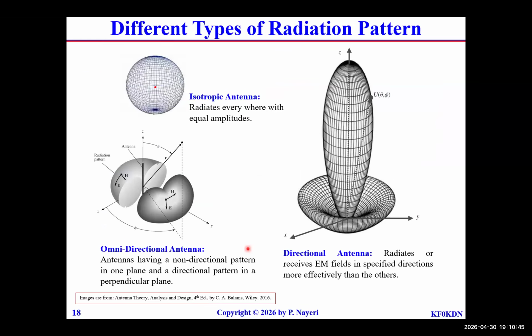So these are basically the three types of radiation patterns that we expect. The isotropic types of antennas, as mentioned, aren't really practical, but from an educational perspective are very fundamental. And if you get introduced to antenna arrays, a lot of the analysis starts with using isotropic type of radiators. This type of antenna, the dipole type antenna, is the one that we are going to talk a little bit about today. And these are higher directivity antennas.